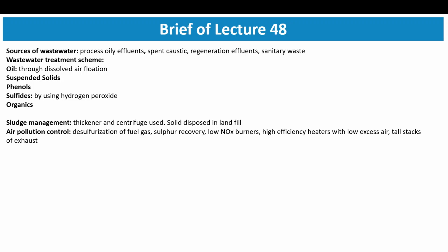In that case, H2S is one of the byproducts, and H2S is obtained by the desulfurization of any of the products or the crude oil. Now to remove the H2S, or to not send it to atmosphere, we send it to strippers, where water or another chemical reagent is provided. So let's say H2S, which is a gas, goes in the upward direction.